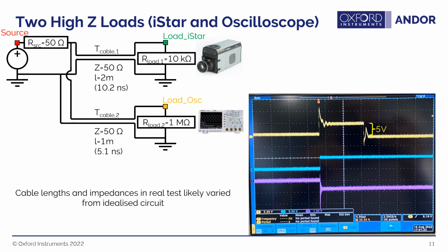And so again, here's a screen trace of an oscilloscope that you want to avoid, because if this pulse height is 5 volts, you can see this goes substantially higher than the 5 volts while it's ringing.